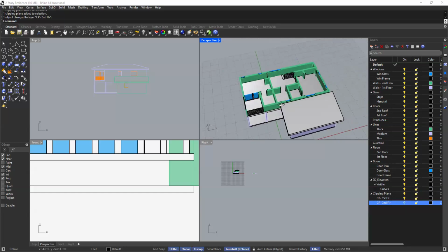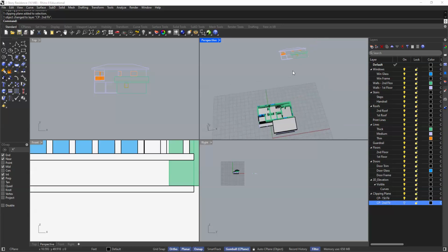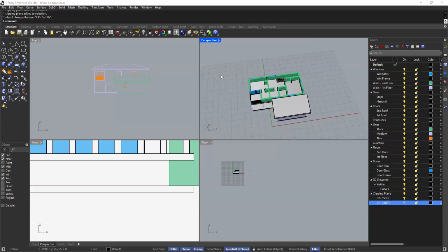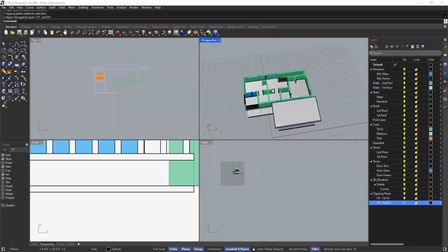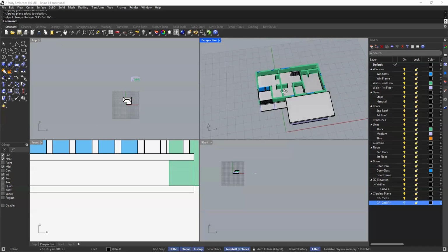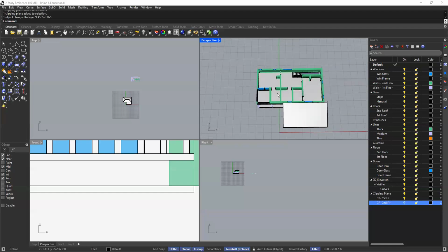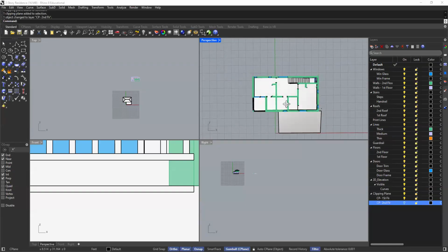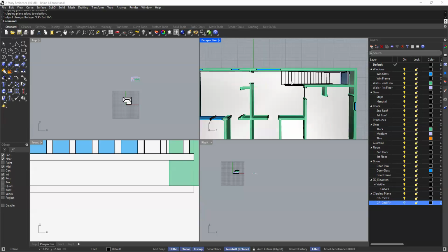And now I'm ready to do the make 2D and follow the same steps as the elevation, although we're going to do something a little bit differently with the floor plan here. So I'm going to go into my top floor, into my top view, so I can see the floor plan, because remember, these orthographic drawings cannot be drawn in a perspective, right?